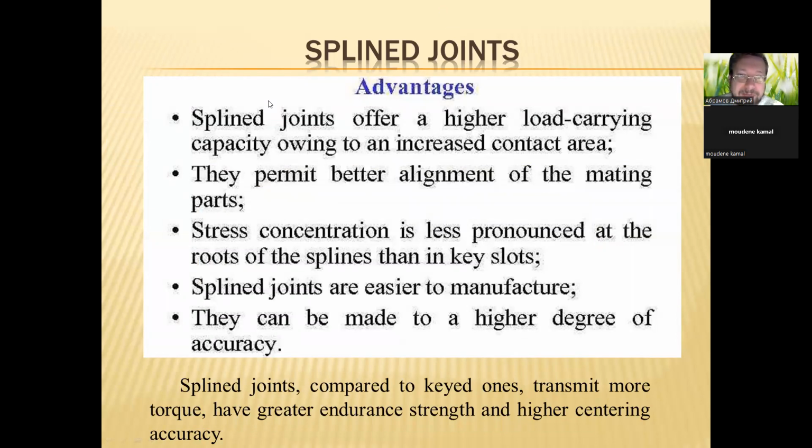Splined joints. Advantages. Splined joints offer a higher load carrying capacity owing to an increased contact area. They permit better alignment of the mating parts. Stress concentration is less pronounced at the roots of the splines than in key slots.